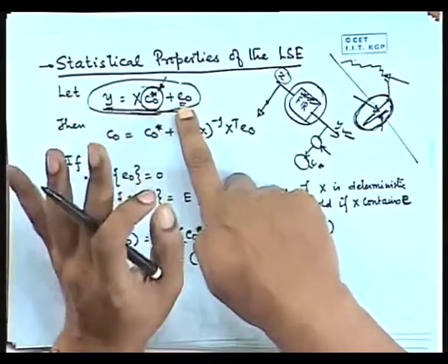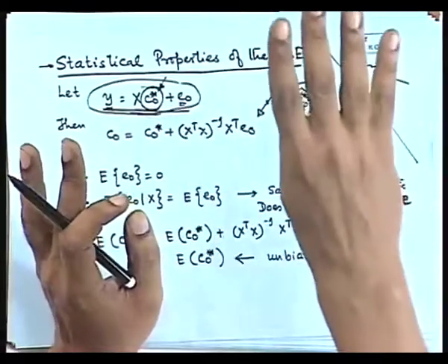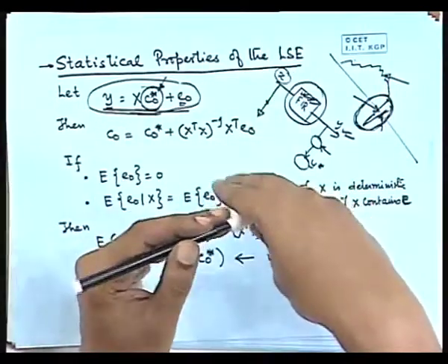It may or may not be the same. In general, it is not the same. The data may be generated, let us say, by a 10th order filter, and it is still valid to try to estimate a second order filter. There is nothing wrong in that. But in this case, we are synthetically assuming that a 10th order filter has been used to generate the data, and we are estimating a 10th order filter. Can I get back those parameters which were actually used in generating y?